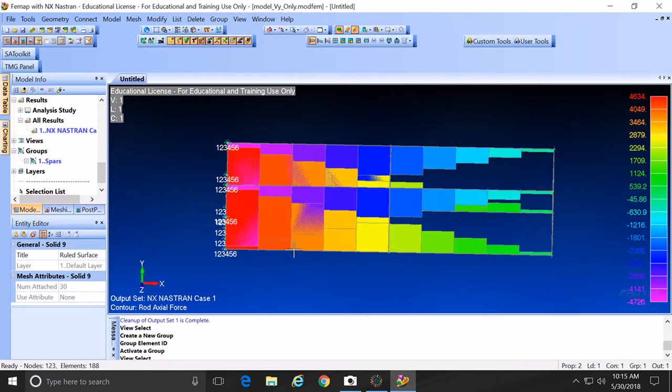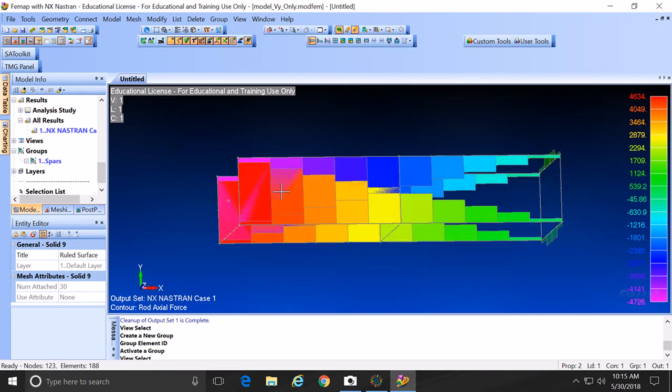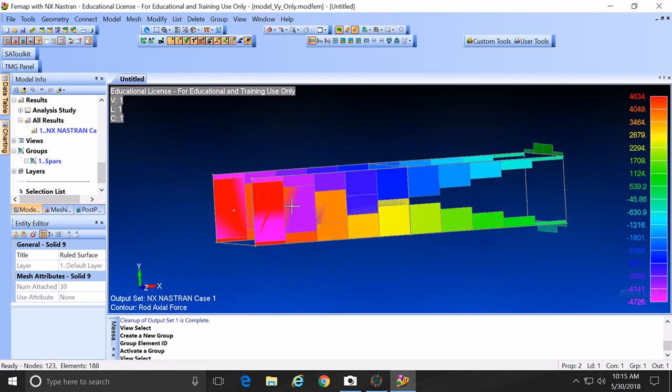So basically, if you also want to remove these ones over here, the boundary conditions, you can go on top of the tree. So this is the load, and you can click on this one. You see on the top, you click that one, they will disappear. You double click, they will show up. But basically, this was the distribution we had.